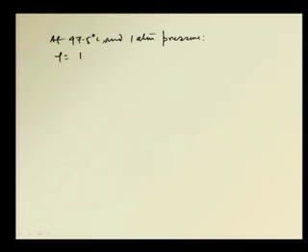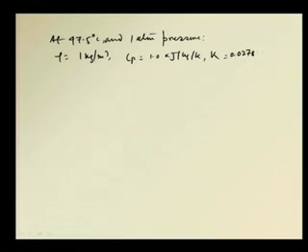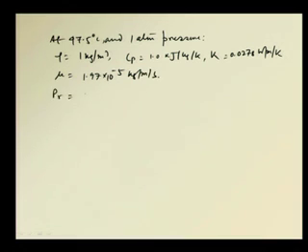So, rho is equal to 1 kg per meter cube, Cp is equal to 1.0 kilojoule per kg per Kelvin, thermal conductivity k is equal to 0.0278 watt per meter per Kelvin, and mu equals 1.97 into 10 to the power minus 5 kg per meter per second, and thus Prandtl number is becoming 0.707, equal to mu Cp by k.